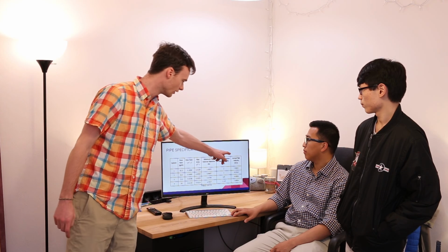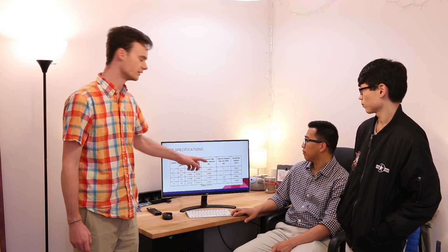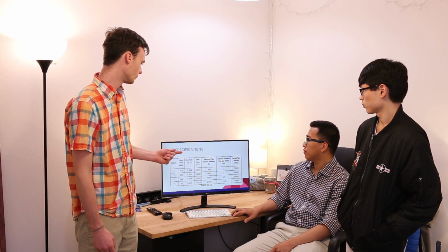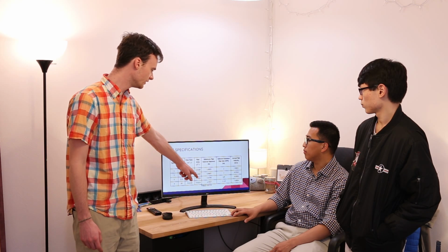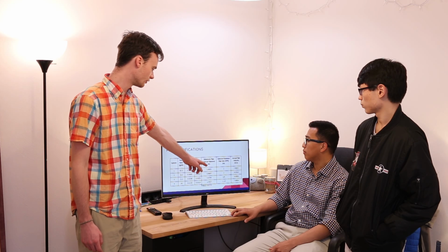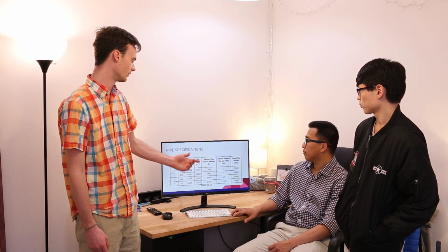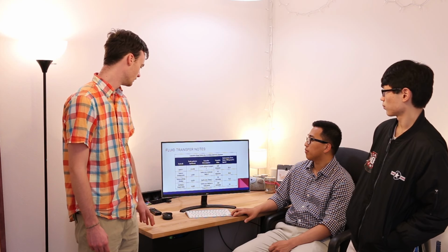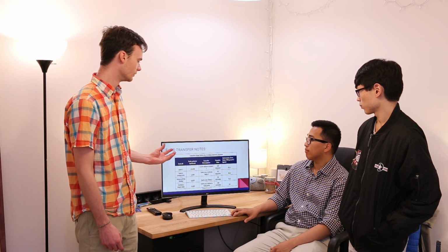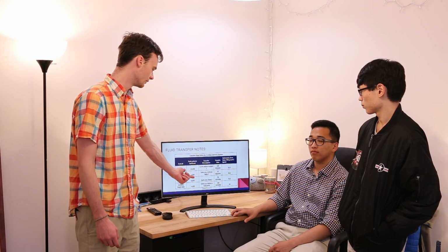Right here is the pipe velocity for the flow rate that we want. That shows what size pipe we actually need, and then we oversize just a little bit to a normal size. So 1.86 inches goes to 2 inches, 0.96 goes to 1 inch, and so on. Right here we have the flow rate that we would need to get those different size tanks to empty, and here are the times that we selected.